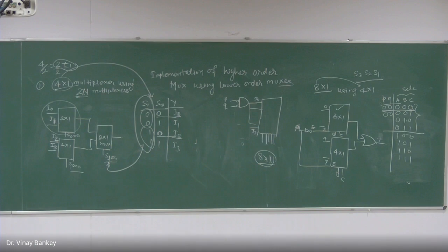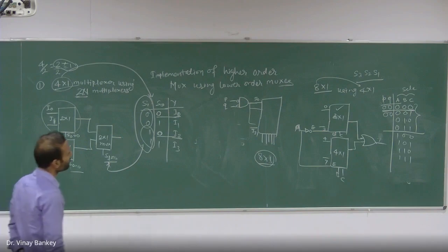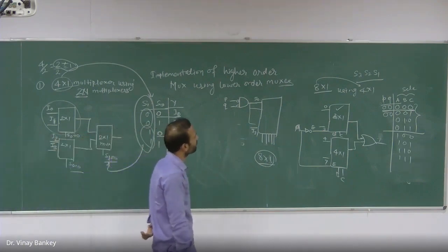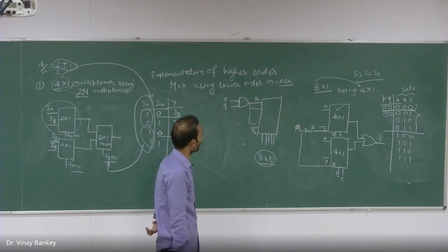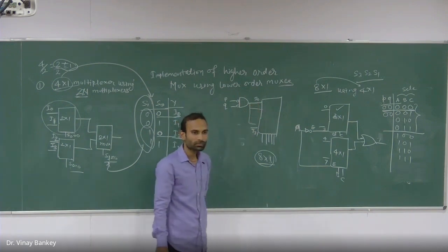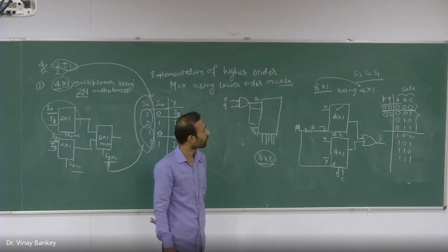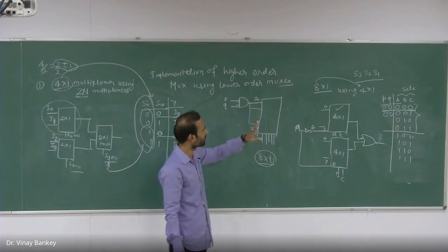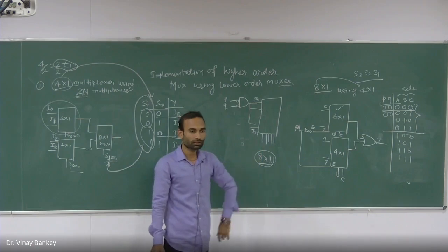What can be a simpler solution than this gate? For example, for the first enable, we can connect P bar, Q bar. Then to the second multiplexer, connect P, Q bar, then P bar, Q, then P bar, and then P. Okay, then what will be connected to I0 and I1 and I2? The inputs that we are using. What input? You don't have any input. You have only 5. Select I0 to I31.